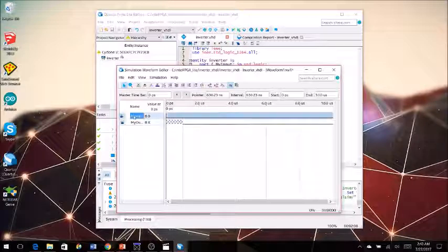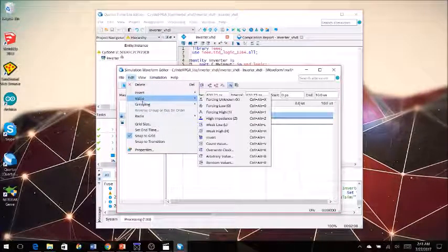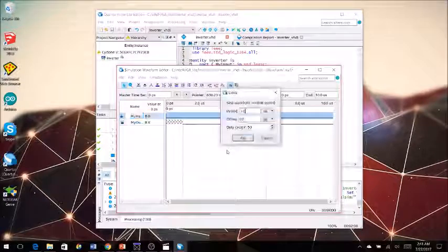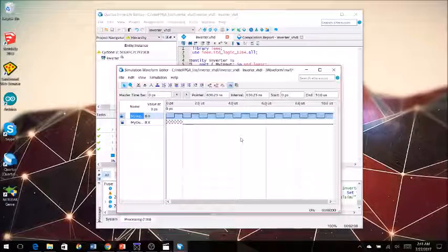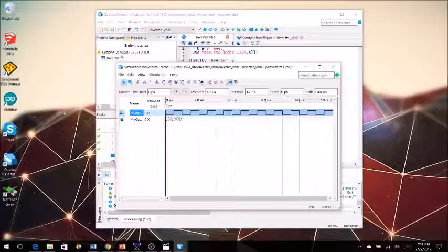And then also I'm going to select the input, and I'm going to go to value, and go down to override clock. And so we can control how this input's working, and go ahead and choose the period to be 1 microsecond.